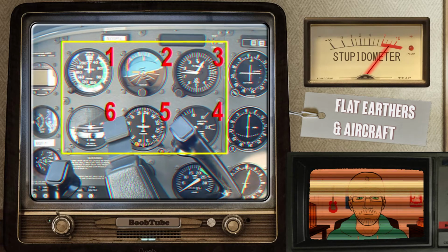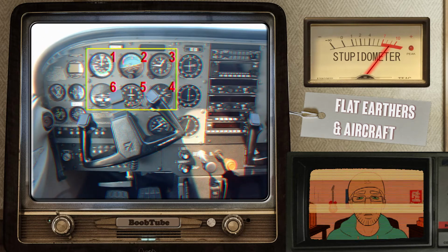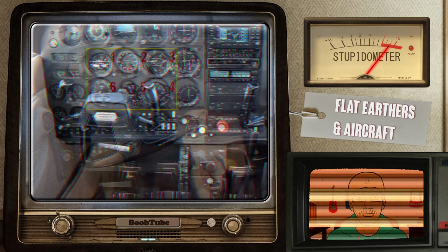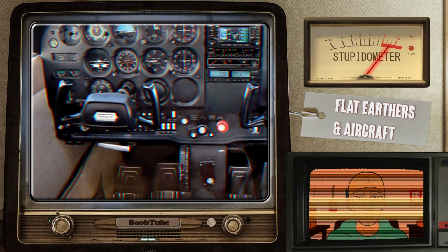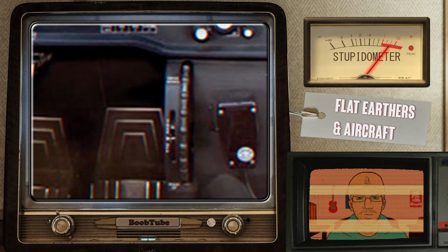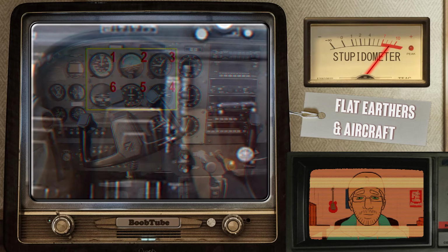Now, the fun part. Once you're airborne and steady, it becomes a dance between throttle and pitch. Typically, you'd set the throttle at around 75% and then correct the pitch to keep the plane level. Now, instead of constantly pulling back or pushing forward with the yoke, you use the pitch trim knob. It simply sets that pull-push offset so you can leave the yoke at neutral position.